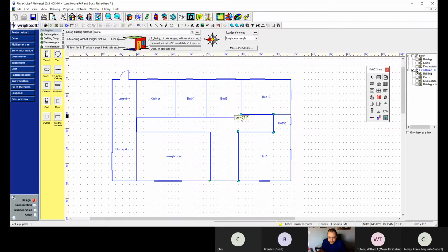Move out of my way, I can't see. Notice it hasn't made it a room yet until now. Oh, okay, now the lines got light, and this one out here darkened up. So now it is all boxed in. Got to put a door in, like so. That door's 3x7, stock doors, so not going to make any changes to that.